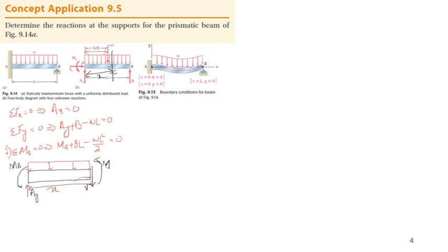And this distributed load I can take as a concentrated load, and that concentrated load will be simply W into x, and this distance will become simply x by 2. Okay, since we are interested in the equation of moment, so let me take this point. This is my C point.